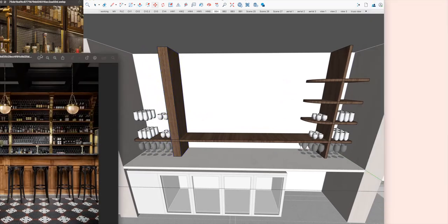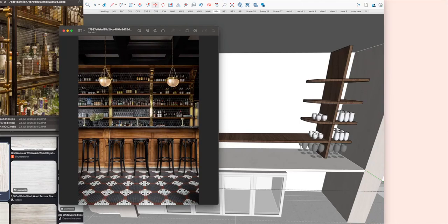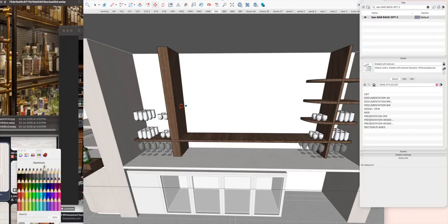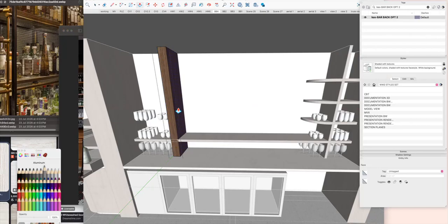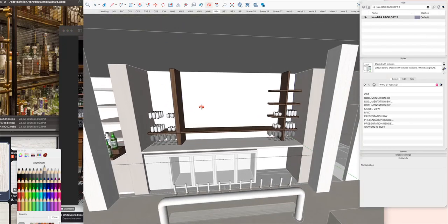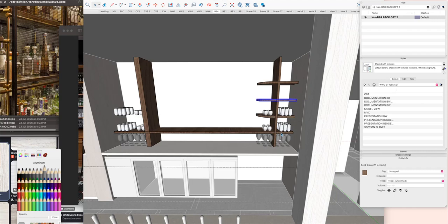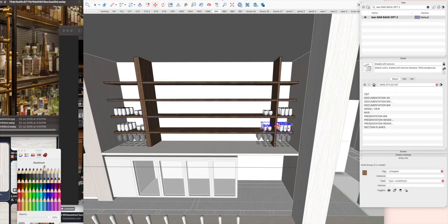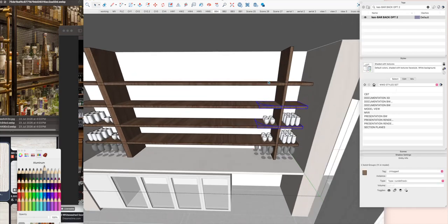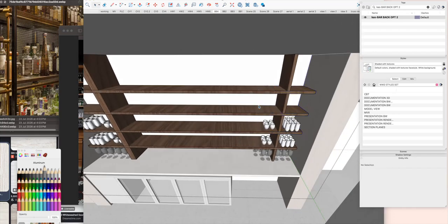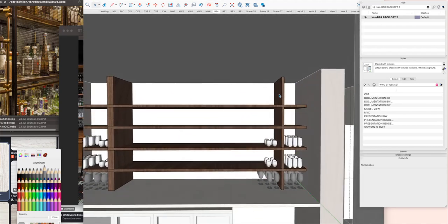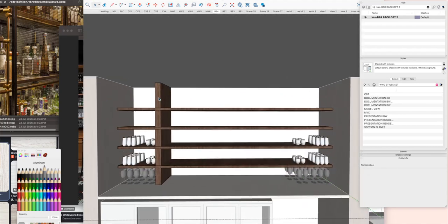This is sort of my reference picture. It may even be a little bit fat now, but they've sort of got the equally spaced. That's a little bit fat. Let's take it back down to about 100. I'm going to copy the shelf spacing here, and then I can tell which ones I've grabbed because it's shorter, and delete them out of there. I'm going to copy one of these to the middle, and I can reference constrain line from point.